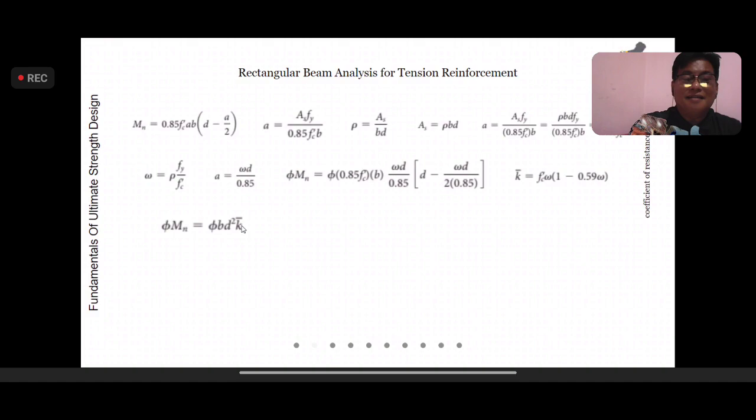The distinction between USD and the WSD, you have a safety factor. So, hindi buo yung kinoconsider natin sa USD. So, 90% lang, tension controlled. So, meron kang buffer. So, kung kumalas ito sa 90%, safe ka pa rin. Kasi meron ka pang 10% na kakarga dun sa sobra na yon. Pag talaga hindi na kaya, magdo-double reinforce ka.